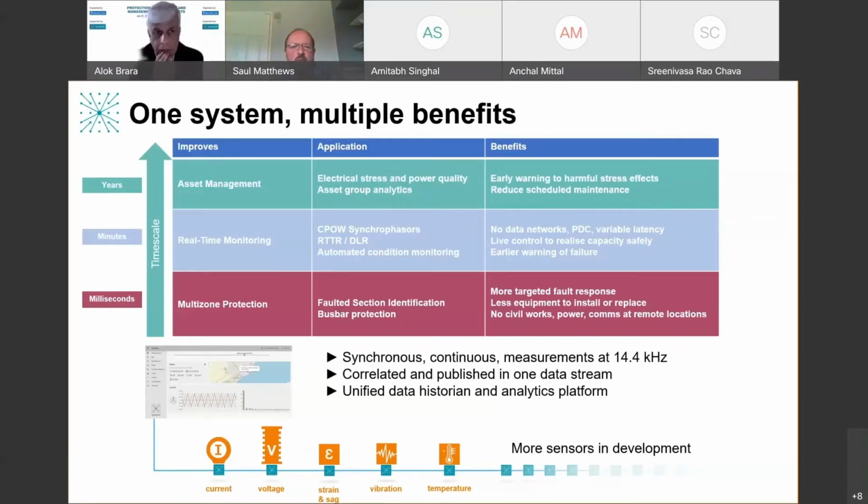So one of the big programs we're doing at the moment is looking at 400 kV underground cable systems, which are powering the capital of Spain, Madrid. And it's not protection, but we're putting sensors on every joint on that underground cable, looking for sheath currents, so leakages of current, losses of power, inefficiencies, and lots of new parameters which will give you an earlier warning of more failure modes than traditional technologies like DTS, distributed temperature sensing, or partial discharge monitoring.